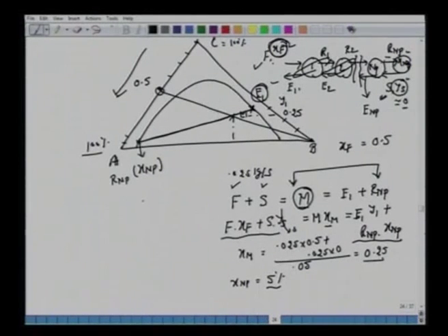So we have E1. Now how do we go ahead? What we have to do here is to realize that we are looking for the del, the difference point. The difference between the streams F and E1, we had a discussion earlier, R1 and E2, R2 and E3, etc., or RNP and S, etc. F minus E1, RNP minus S, it's a del point, it's a difference. The difference is conserved. F minus E1 is RNP minus S, or R1 minus E2, any trace, this is constant, del. So that's the advantage of working with del here.